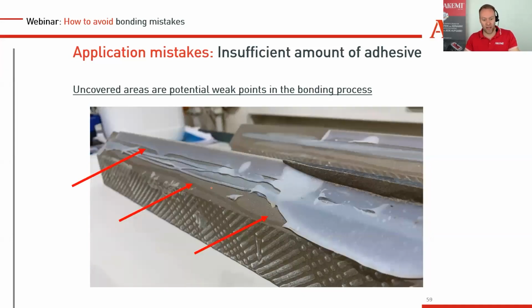And then I say okay, that's not enough glue. You can see here there's a lot of air inside. No glue there. You can see the glue was sticking. The glue was proper because it ripped out some part of the ceramic here, so the adhesion was there. Here in the front, because it was small, maybe they pressed together a little bit. There was enough glue there, but later on there was not enough glue.